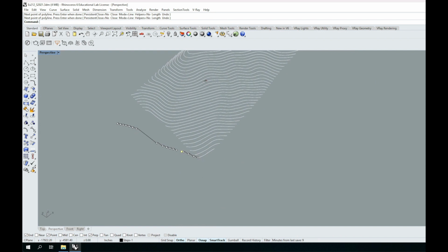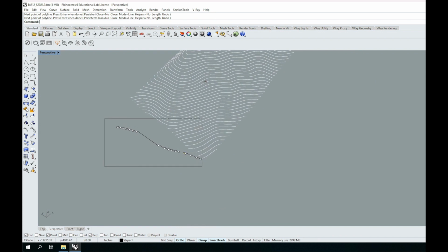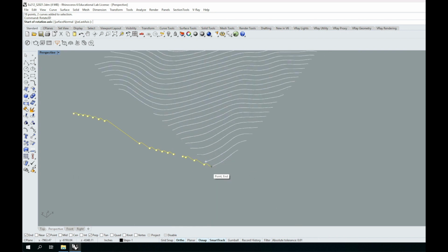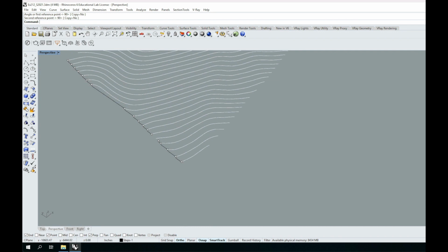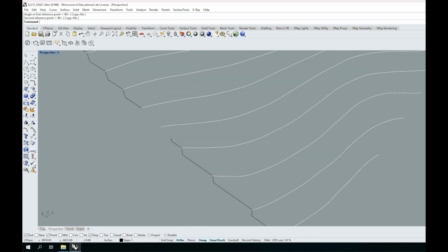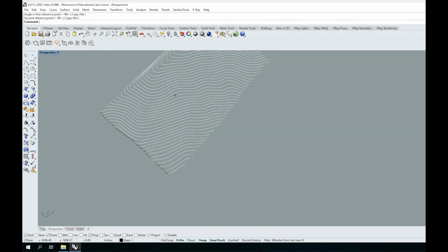Now after I've drawn all of that, I'll go ahead and select all of those. There they are. I'm going to use that Rotate 3D command again. There's Rotate 3D. We'll start at the same first point right there. We'll go off in the Y direction, and we'll go from being flat to being vertical. And yeah, you can see there was an error there. This point didn't get on the end, so I wasn't able to make that set of steps. So now that I've done it with that method, I have my set of steps. I'm reasonably happy. We'll fix that problem next class.